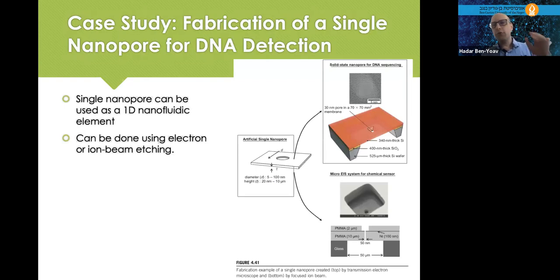Now, to choose which kind of etching is the best way, you look at recipes of other colleagues or some kind of experience, which kind of recipe to use, or if you've seen papers. And if not, you can choose your own recipe and then try to optimize it, see if it works. If not, change some parameters, and you can try trial and error until you get your process correctly.